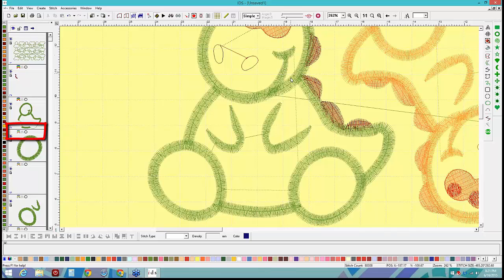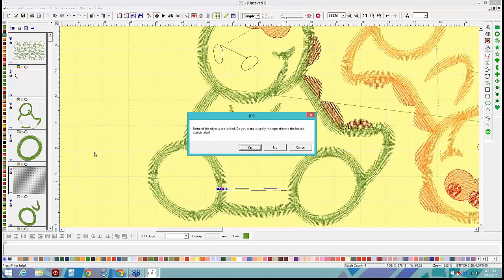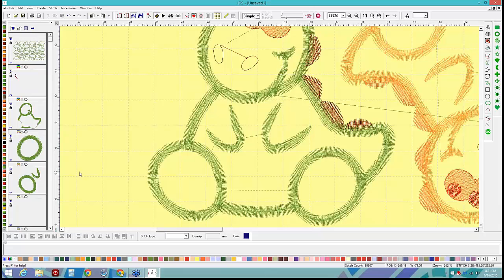If I move this, see the dashed line right here? If I place a trim in, which is a machine code to trim the thread and then move to this, you can see that disappears. Now I have this section too with it. It has dashed lines, but it is showing up as a section. So I'm going to do the same thing. Select it and press Control Delete and say yes, delete it. And then I'm going to put a trim here as well.